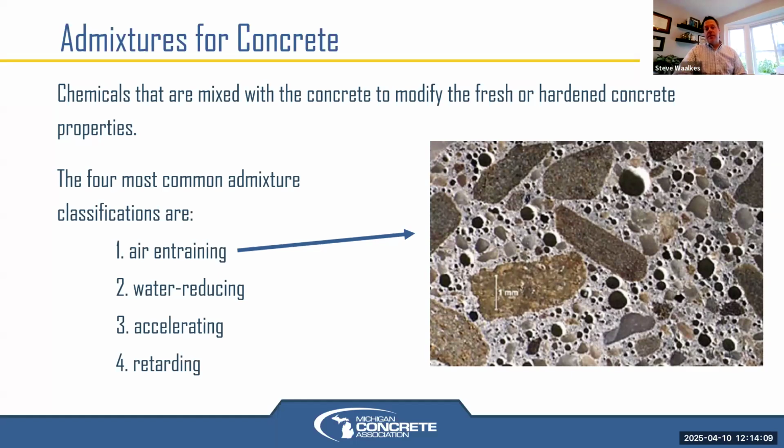But regardless, the main thing you get to achieve freeze thaw resistance is having air entrainment on a microscopic basis. So air entrainment admixtures are surfactants, which means that they act just like soaps do in the presence of water. Liquid soap in the presence of water, when agitated, creates foam, creates air bubbles, distributed throughout the cement paste, that gives us freeze thaw resistance. They act as little pressure relief valves, like shown in the photo there.